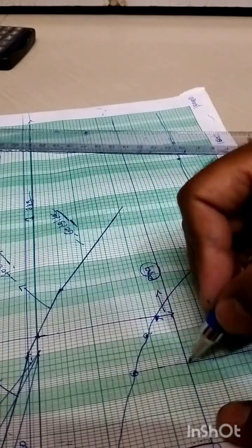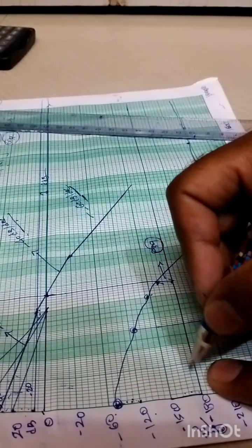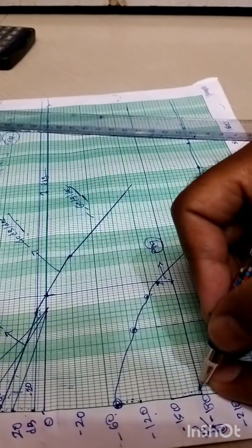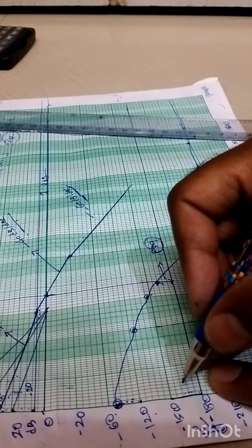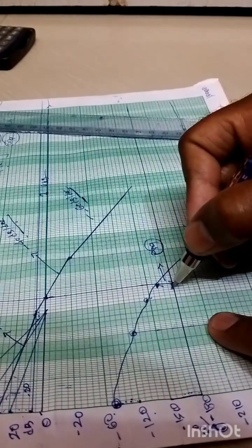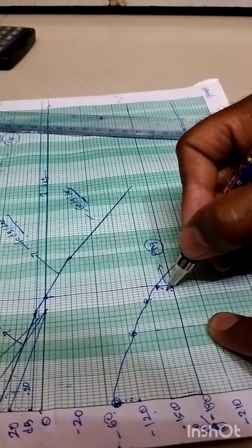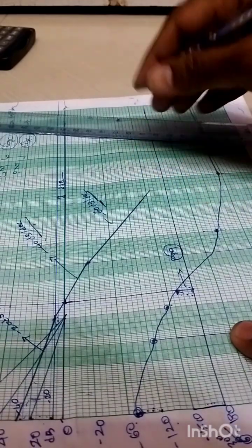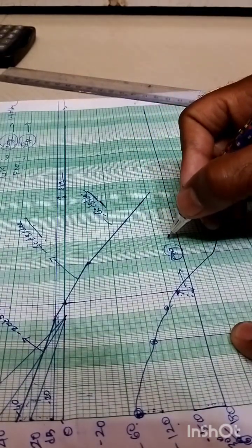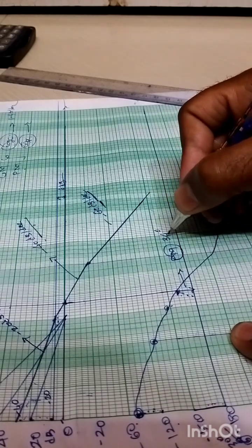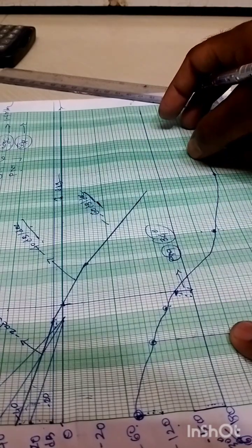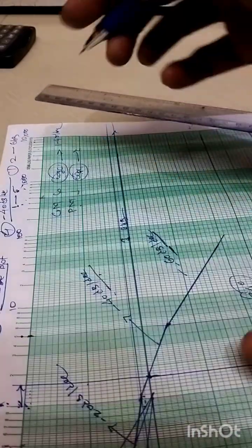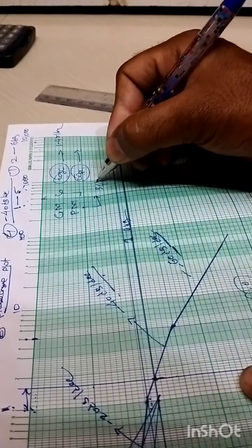Now in case of this phase margin, as each block stands for minus 30 degree, the value for each division is how much? It is 6 degree, right? So here we are having how many divisions? This is 1, 2, 3, so there are approximately 3.5 divisions. So phase margin equals 3.5, 3 sixes are 30, which means it is 34 degree. Phase margin is how much? 34 degree, right? Here phase margin equals 34 degree.